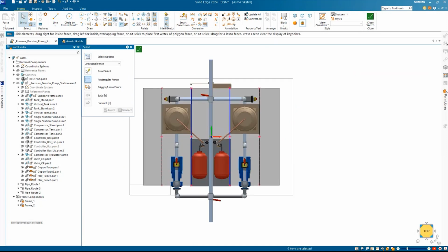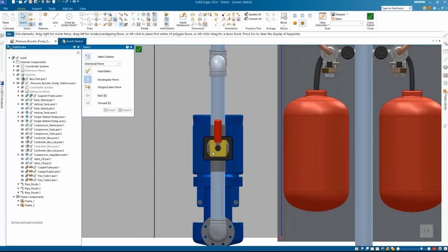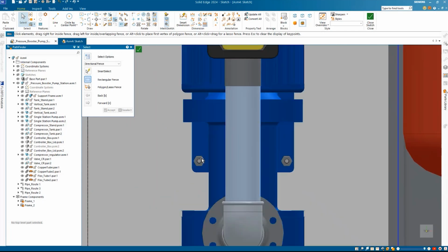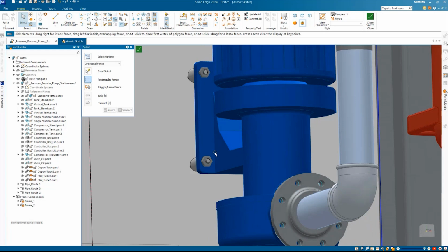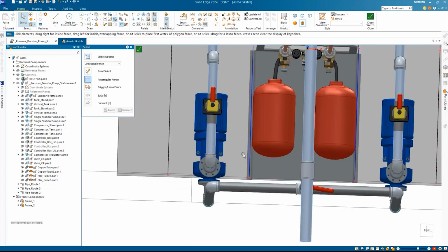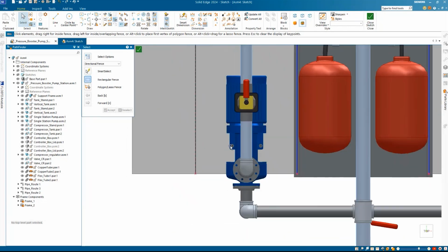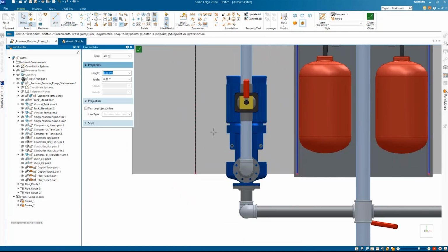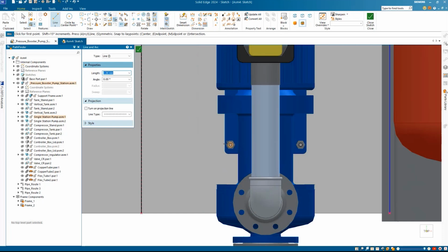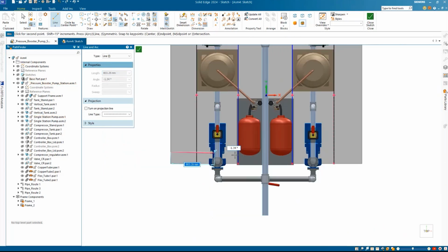And one more thing I also have to do is create support or the frame members for this motor. So this motor is bolted in at 4 different locations. So I need to create 2 frame members for the motor. So first, let's create one for this. That is, I want it to come from the midpoint, connecting the edge.